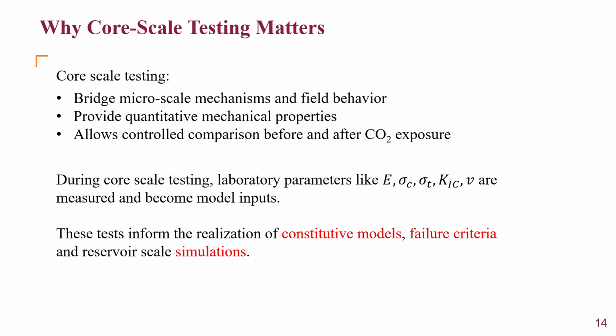Now, during core scale testing, engineers would normally look for parameters like Young's modulus, compressive stress, tensile strength, K1C, Poisson's ratio, etc. These properties will serve as input for constitutive models. They will help us create some failure criteria.